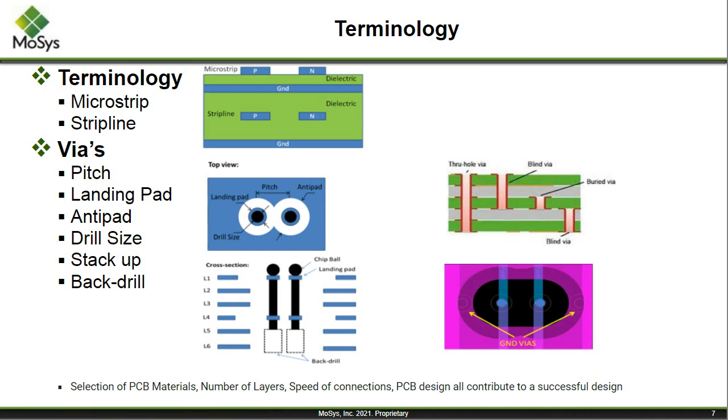And then you go up and down, and when you think about signaling, it's the edge of the signal that really causes a tremendous amount of issues in routing. It's not the DC portion of the signal, it's the edge, the rise and the fall times that are going to be of issue. So when you have that, any source of capacitive or inductive discontinuities or changes is going to cause a tremendous amount of dispersion within the signal itself.